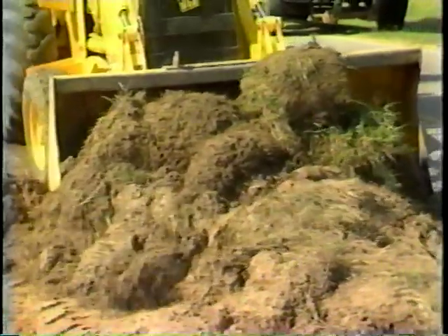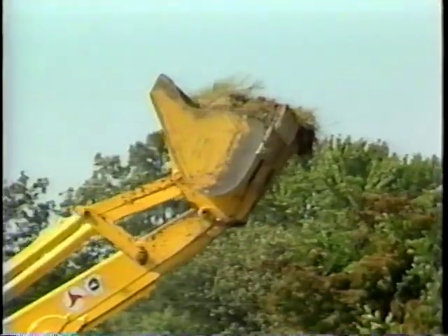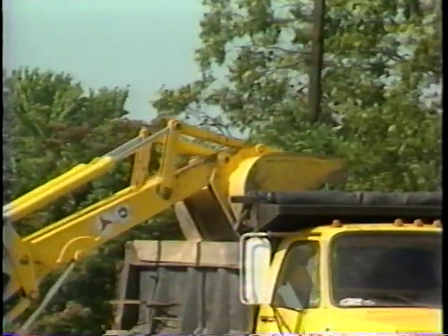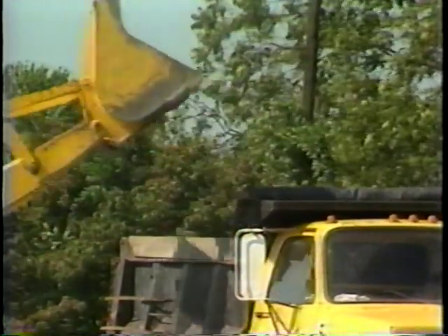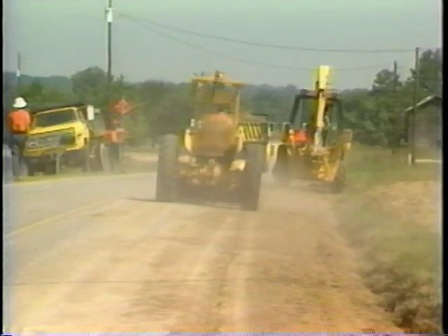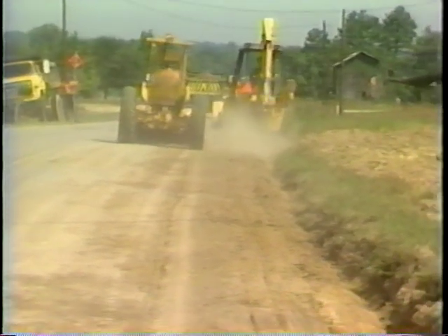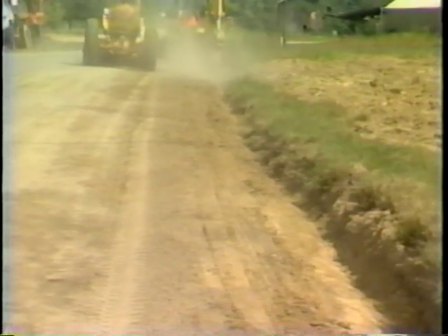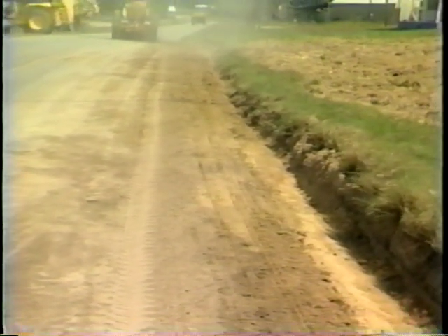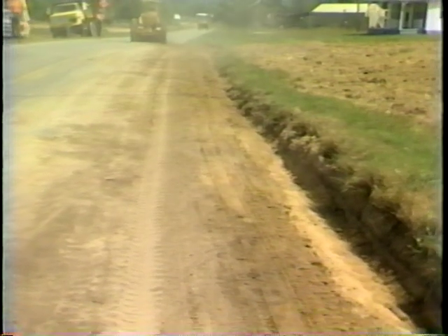Behind the motor grader, a front-end loader picks up the windrowed material on the edge of the pavement. Load the material into dump trucks and haul it away to a waste area. If necessary, broom excess material off the pavement with a power broom. The repaired shoulder is flush with the edge of pavement. No buildup remains. Place seed and mulch as needed to reestablish vegetation on the unpaved shoulder.